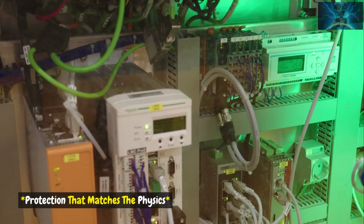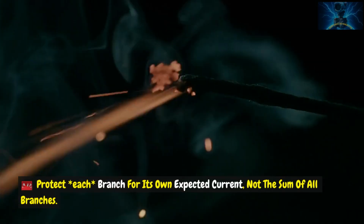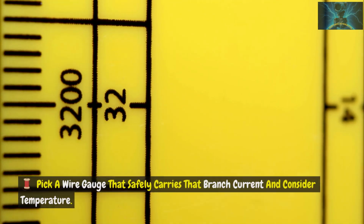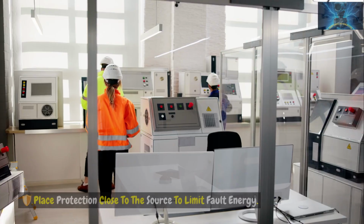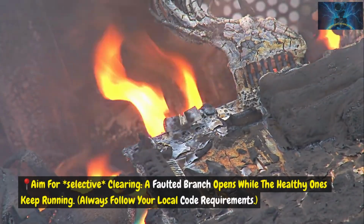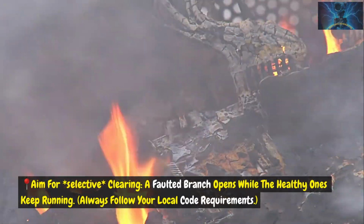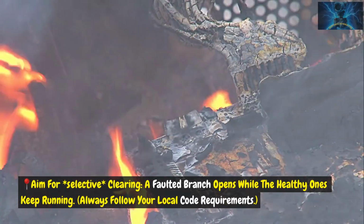Protection that matches the physics. Protect each branch for its own expected current, not the sum of all branches. Pick a wire gauge that safely carries that branch current and consider temperature. Place protection close to the source to limit fault energy. Aim for selective clearing. A faulted branch opens while the healthy ones keep running. Always follow your local code requirements.